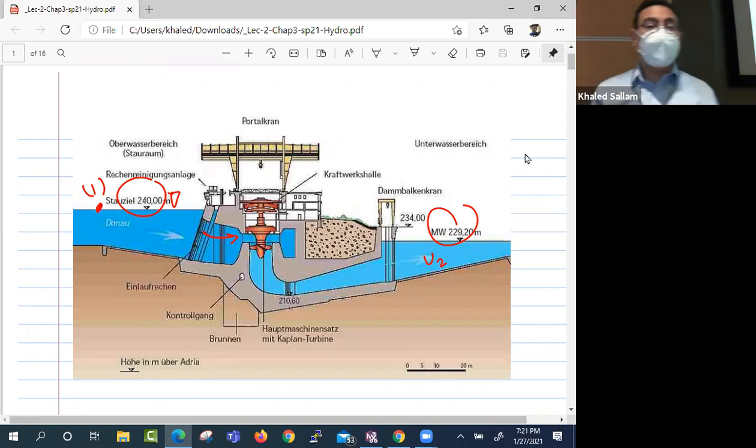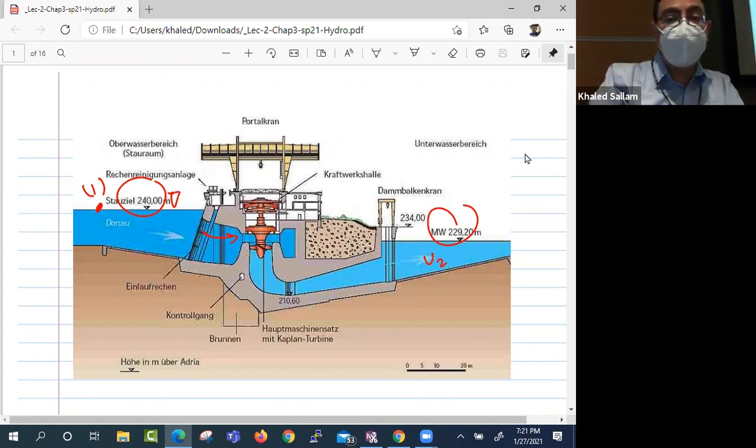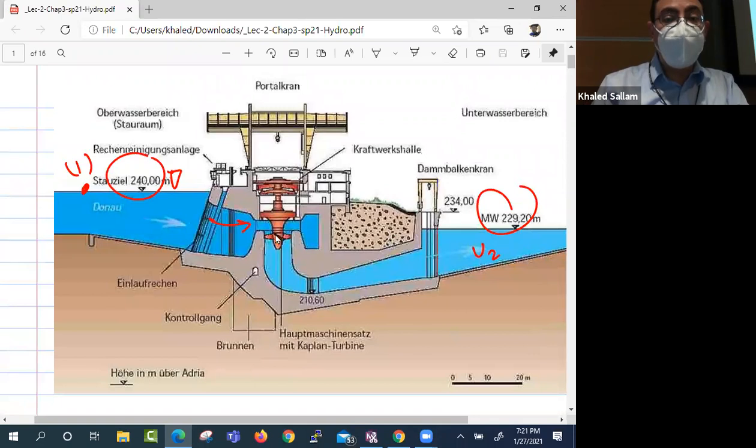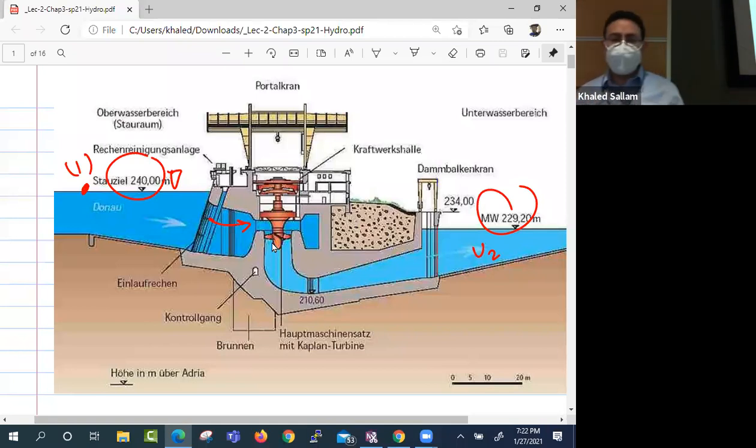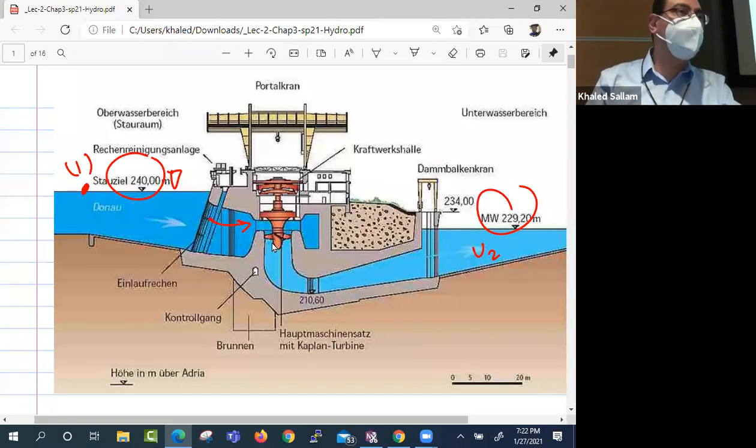So for example, over here, this is a hydraulic turbine. The rotor is the part that's rotating, and in the case of the turbine, we also call it the runner. The rotor in the pump is also the thing that's running around, and in the case of the pump we call it the impeller, right? And say in a submarine, the thing that's rotating is a rotor, but we call it a propeller. So those are names for the thing that's rotating. There is something rotating, that's the rotor, and there's something fixed, not rotating, and that is the stator.